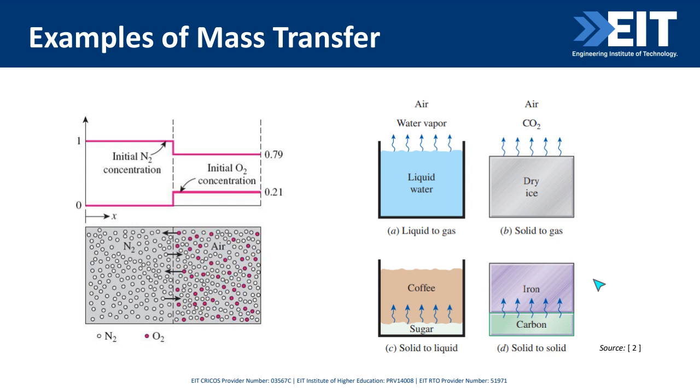In many applications, we want to harden the surface of a material, whereas inside of the material, we want it soft. So how do we make it hard? We put more and more carbon on the surface. So how do we diffuse carbon on the surface? Using this process. So the diffusion process is a case hardening process, a metallurgical process. Metal industries pretty much use this concept.